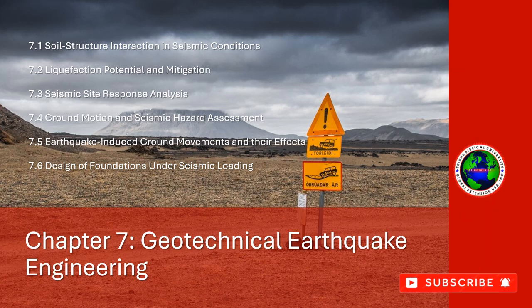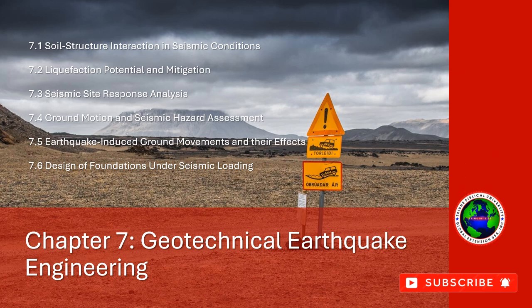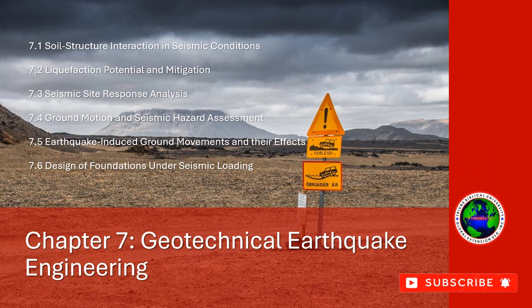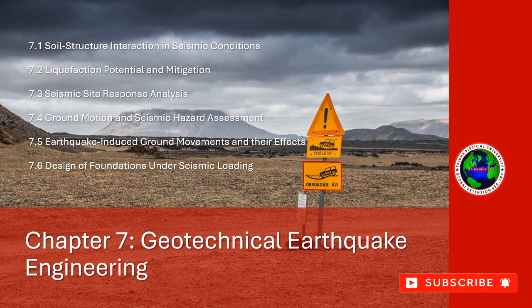Key factors affecting seismic loading on foundations include: 1. Dynamic soil behavior. During an earthquake, soil behaves differently than under static conditions. The ground can experience horizontal and vertical displacements, liquefaction, or settlement, all of which affect foundation performance. The soil shear strength and compressibility are critical to understanding how it will behave under seismic loading.